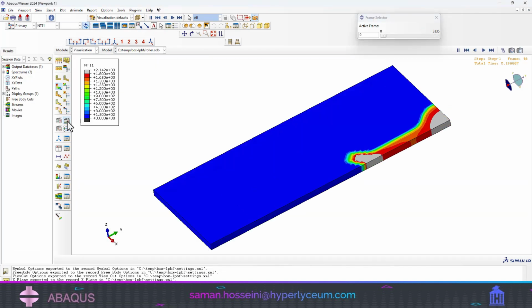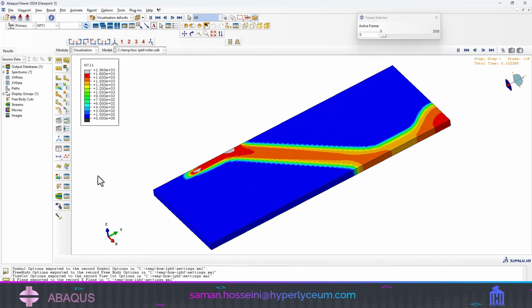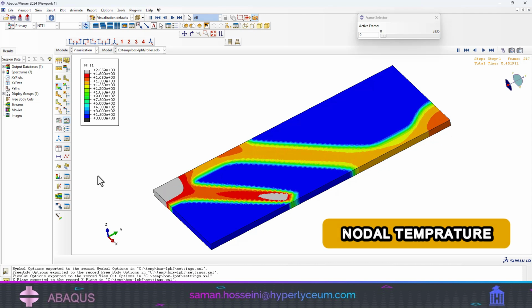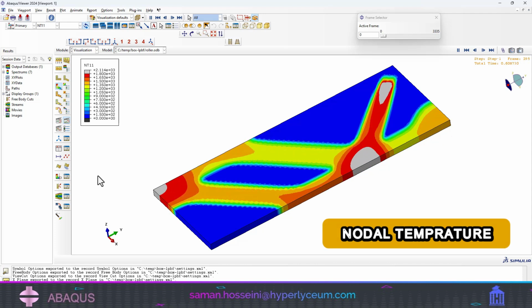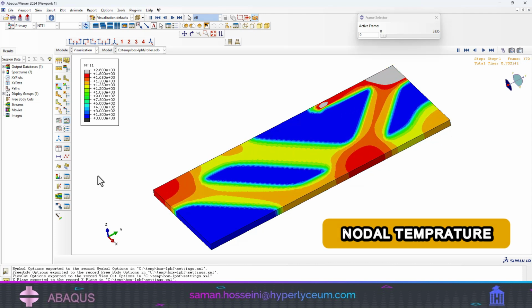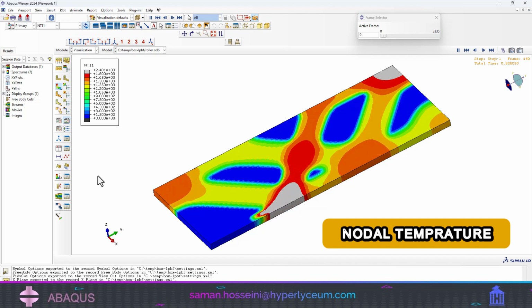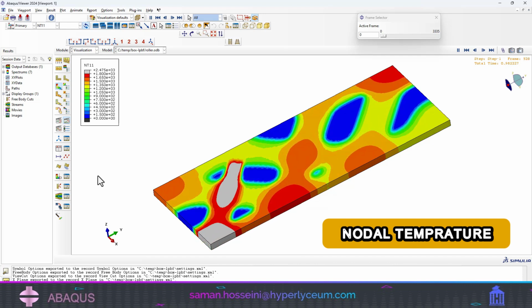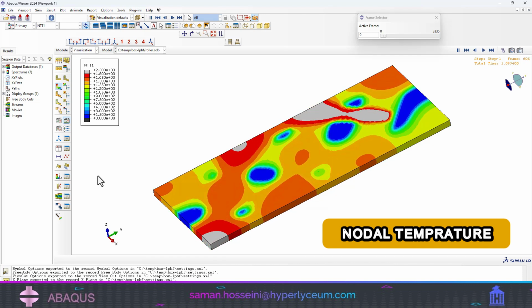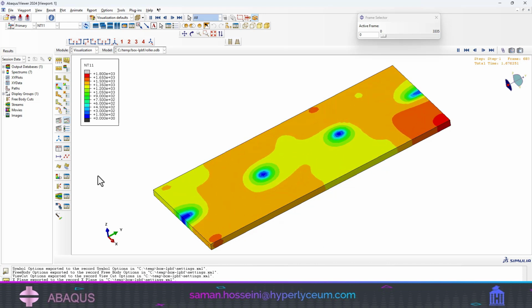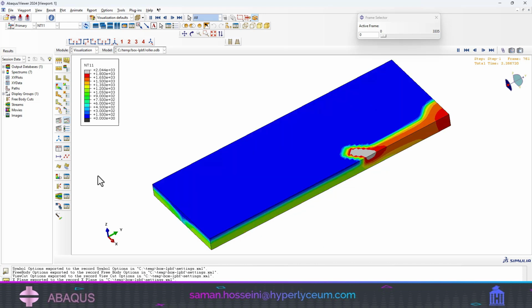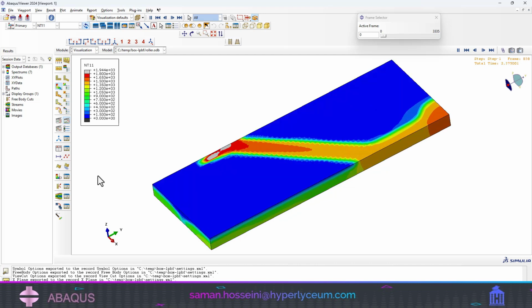Here's an example of printing a box using the laser powder bed fusion method. This process is trajectory-based powder bed fabrication. At the beginning, a layer of powder is applied, and then the heat source moves according to the specified pattern, causing the powder to melt and subsequently solidify upon cooling. The infill density is crucial here, as it directly affects the final porosity.